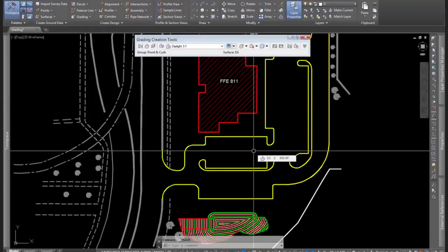And if we step back a little bit and we think about how is a parking lot graded, what is a drainage pattern in a parking lot? It's often pretty simple. It's drainage to this or that catch basin, perhaps a ridge or a swale here and there. And the overall drainage patterns are fairly straightforward. They can get a little detailed around buildings and things like that, but for the most part, you're sheet draining this way or that way at a 1 or 2 or 3%, depends on the scenario.